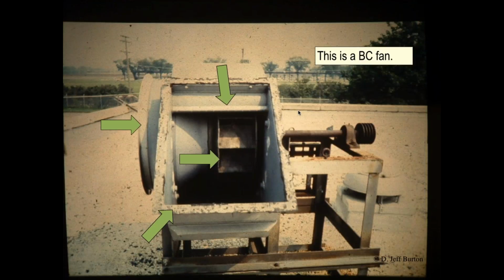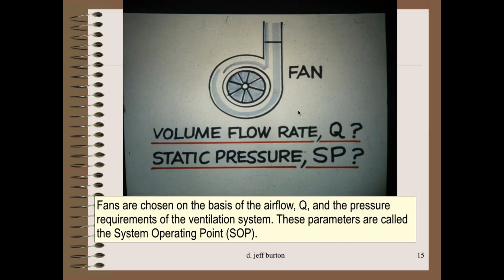Okay, here's a backward curved fan. And obviously, there was a motor here, right? This is opened up for maintenance or something like that. There's a motor here, and this had a pulley drive. Had a motor probably mounted here somewhere and pulleys hooked up to it. So you could actually change the gearing, the pulleys on this, so you could change the revolutions per minute and how much air it moves and what the static pressures are. We're going to talk about that later on.